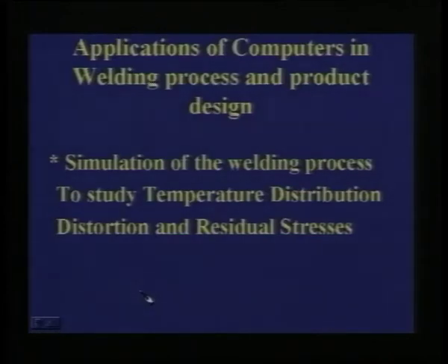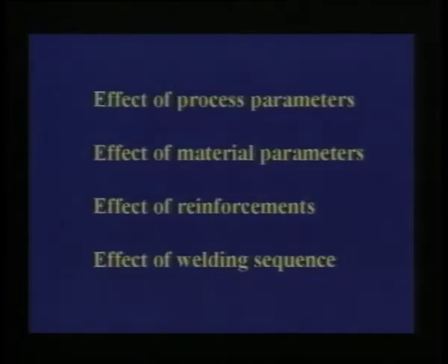So, what we are seeing now is the application of computers in the welding process. Let us look at the next thing. We are going to study the temperature as well as the residual stresses. Now, why do we study this welding problem? We can determine the effect of process parameters, for example, the speed with which you move the arc, or the effect of the voltage and current that you apply, and so on.